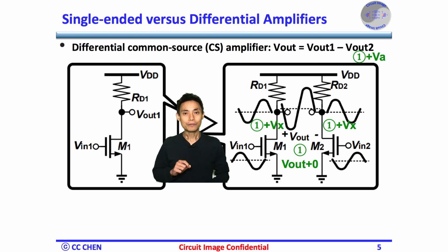Furthermore, the waveform of Vin1 is the inverse of Vin2. Similarly, VR1 will be the inverse of VR2 in polarity. Therefore, only the differential signals at the input Vin and the output Vout are applied in the system. What happens if the VDD or input common mode voltage varies?